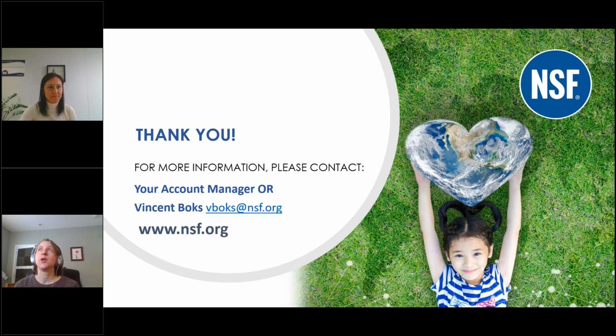Brass is the only component of faucets that is allowed to contain lead. So typically we see more lead leaching with the greatest surface area to volume ratios of brass in the faucet. Faucets that have a higher surface area to volume ratio of brass, or higher lead content brasses, will tend to extract greater levels of lead.